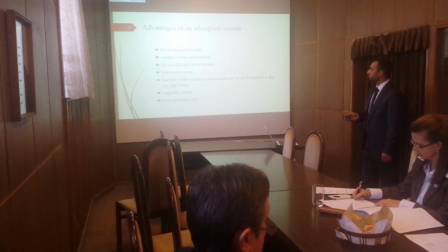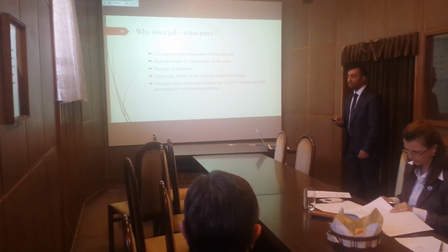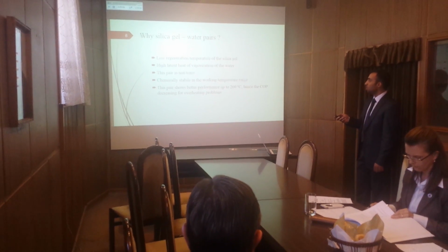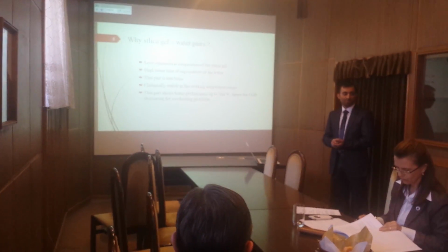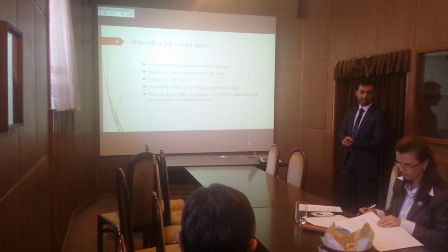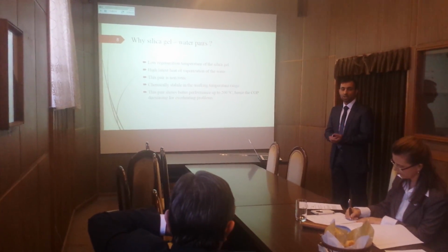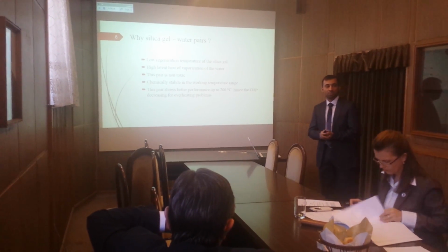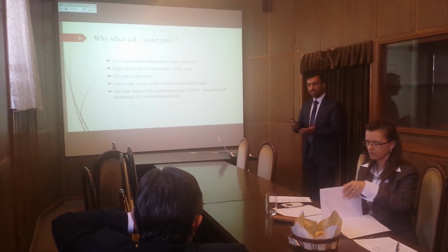Why did I choose silica gel water? Because there are a lot of pairs, but I chose the silica gel water pair because of the low generation temperature of silica gel and the high latent heat of the water, and also this pair is non-toxic and chemically stable in the working temperature range, and also this pair shows better performance up to 200 degrees centigrade.